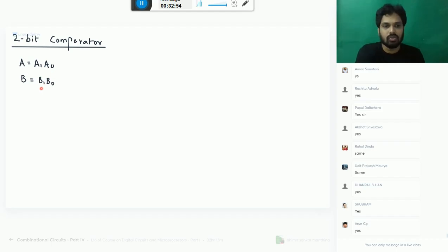Please listen here. If a particular bit AI is greater than BI, single bit, we represent that with X. What is X? It is given by the equation AI into BI bar. That part is already done. Yes or no?